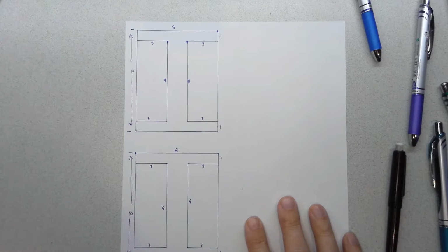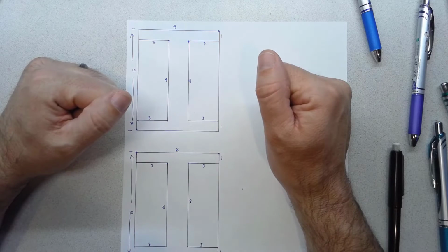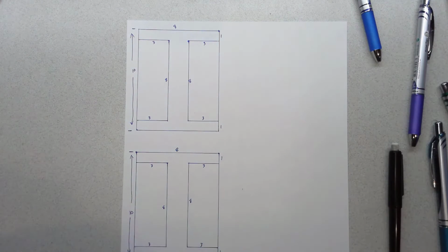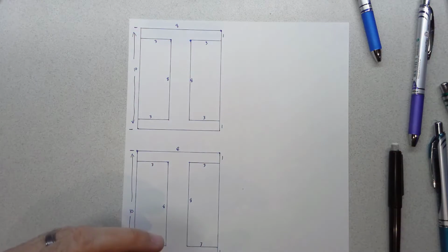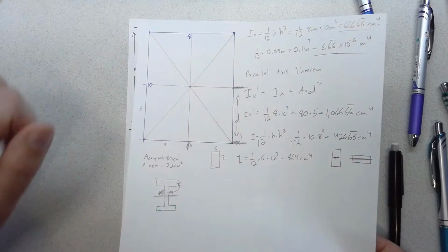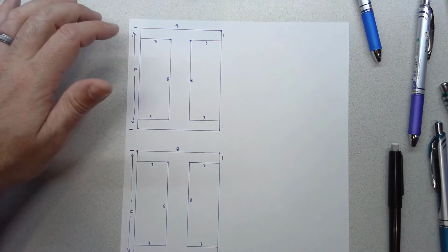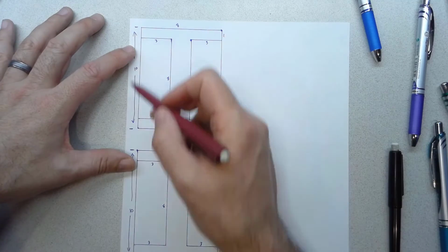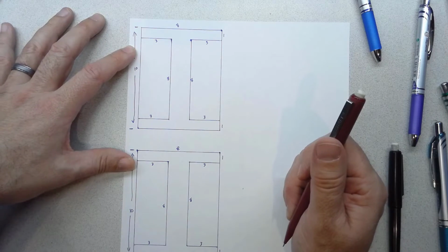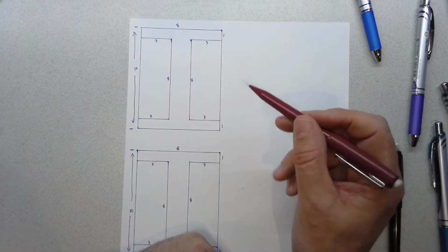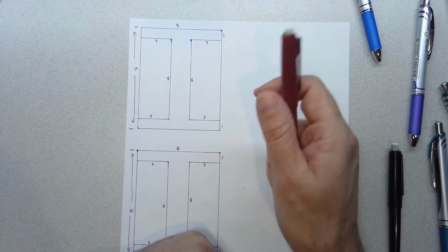I'll try to be clear when I'm using I for the shape, an I-beam shape here, versus I representing our moment of inertia. So there's two different ways we can look at this I shape, starting either from the whole rectangle block that we've done before, right? We found I about a simple rectangular shape. We want to look at this composite I of just the I-beam shape. We can do that either by finding the whole rectangle one and then subtracting out these two sides, or we can build it out of three parts. And it's a little easier to start by looking at it as the whole rectangle and then taking away the contribution of these two pieces along the side.